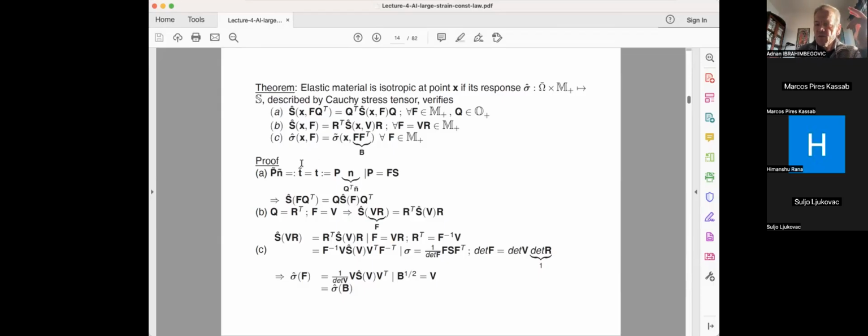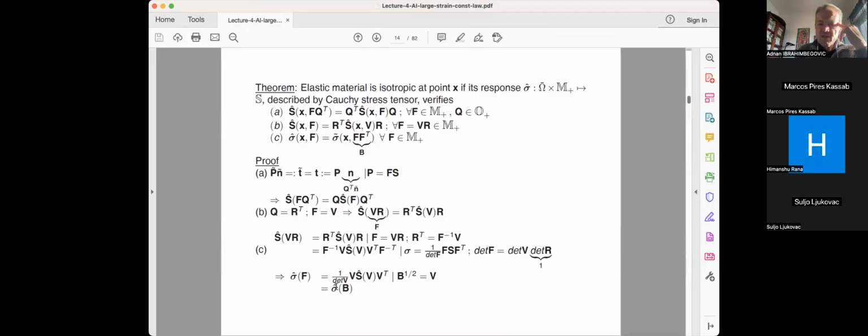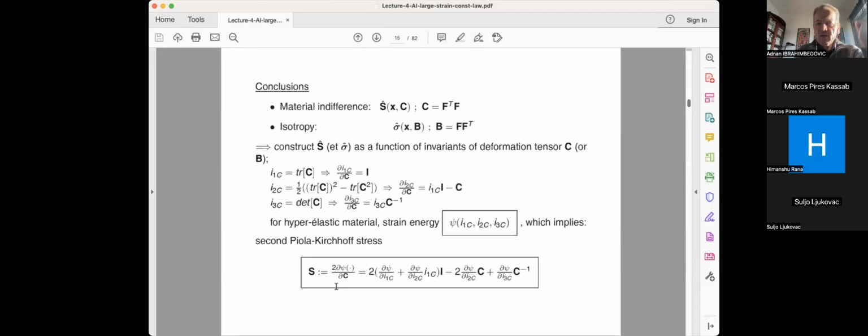We said we are computing the material formula of the traction, and then in the rotated configuration, this traction is equal to Q transpose times n. That gives you a description from here and a description from there. Then turning the Q into the rotation that features in the polar decomposition, you have the second line, and then finally recalling the connection between the second Piola-Kirchhoff and the true Cauchy stress, you can come up with the last result. All the details are in the book if you really care about looking into them. I refer you to look there carefully.